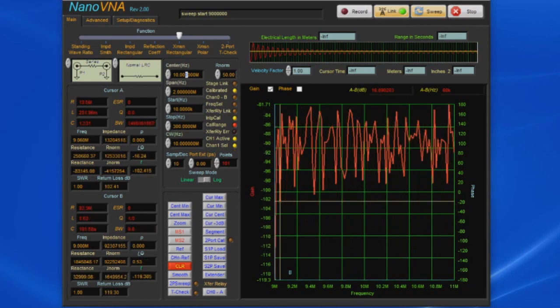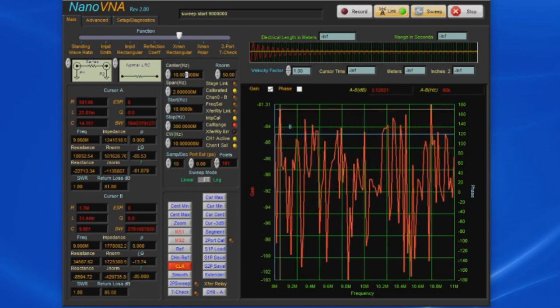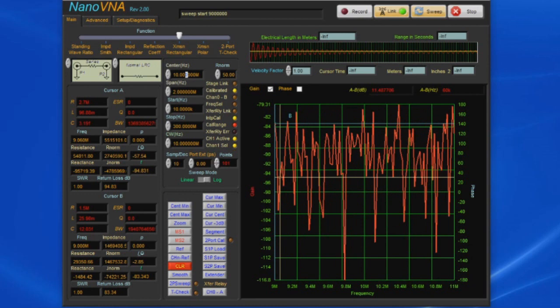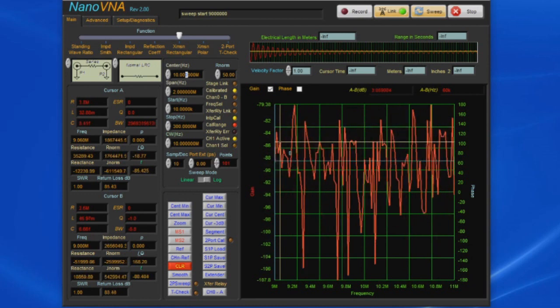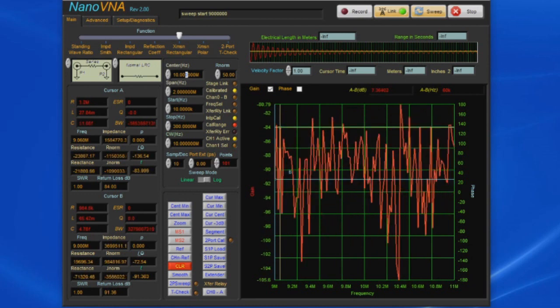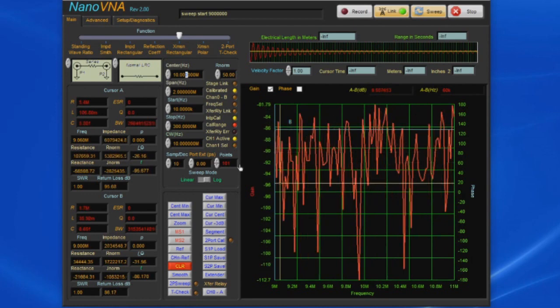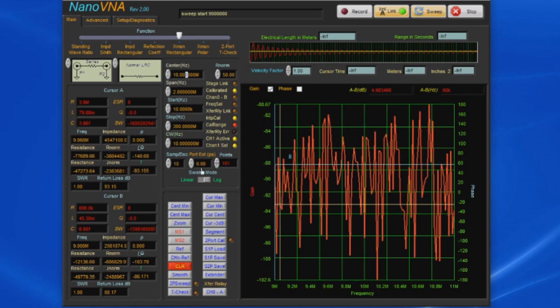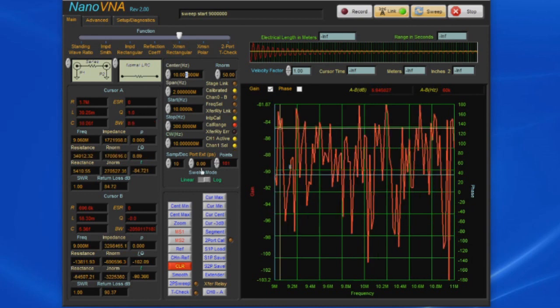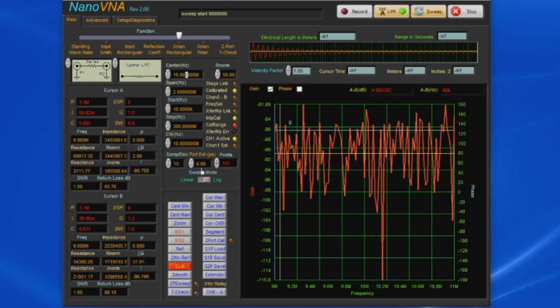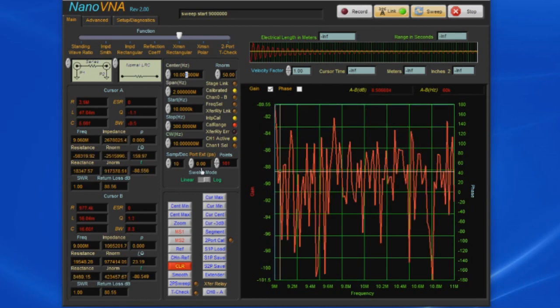Now again, with some firmware running on the H4, you have the ability to run above 101 data points. So the way that the software works now, you can actually change the number of data points. You see it's programmable, and you can save this into the default file. So the next time you run the application, for example, if you've set this to 401 data points, the software is expecting that the Nano has 401 data points.